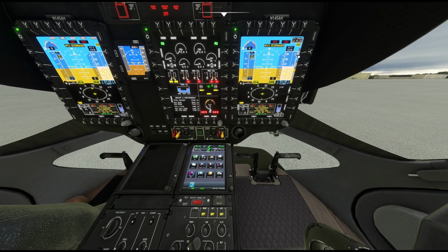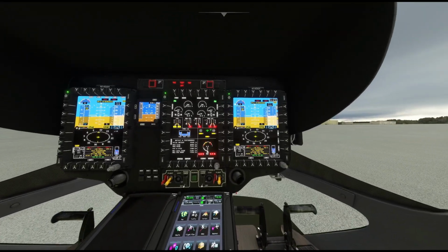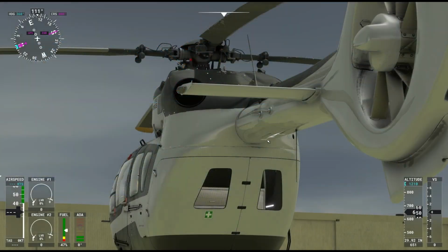And then the last thing right here is your radar altimeter. That is the radar bouncing a signal off of the ground. And actually, right here, these are your radar altimeters. So it sends a signal, bounces it off the ground, and reads the signal coming back. It basically sends a waveform down to the ground and then measures the phase shift of that waveform as it gets back here. And the further shifted that waveform is, the higher up the aircraft is.